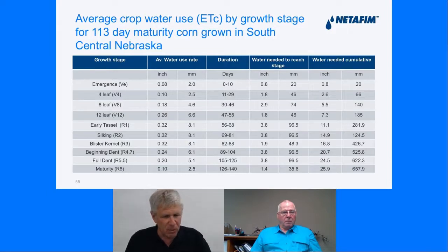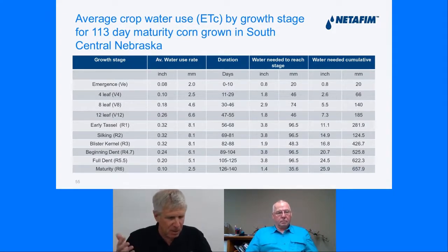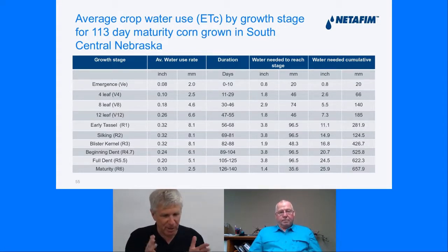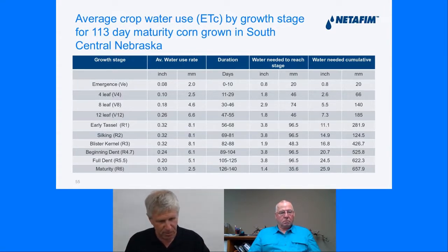And then, in order to design the irrigation system to stand for the peak demand, let's say if we're speaking about corn in the United States, the peak demand will be at the end of June, during July. It can be different in different locations. It can be 0.25, 0.3 inches, or can go also to 7 to 8 millimeters. We create a certain water table that is based on historical data, and we know in advance how much water we need to apply to each hectare of corn, soybean, or whatever, and according to this, we can calculate how many acres or hectares we can cultivate in a specific growing season.